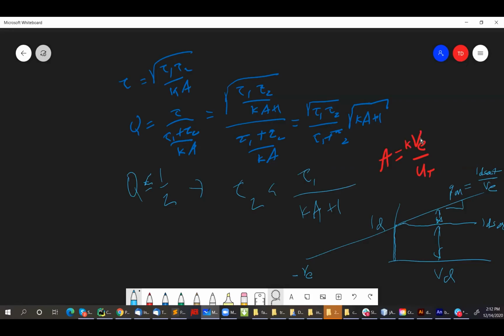But in reality, is that what it is? So finally, after a long, long time of trying to puzzle out why the thing wasn't getting stable at Q equals a half, I did a simulation. What is the actual open loop voltage gain of the amplifier in the photoreceptor, which is this little, very simple amplifier, just a constant current IB with this FET. So this is VG and this is VD. And remember, this is the ideal transistor. It has this parallel conductance, which is GD, which is ID sat over VE.